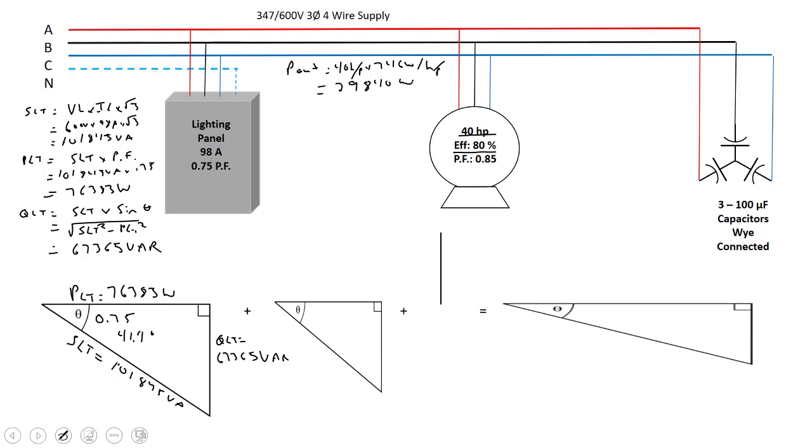All right, now I can sub that into our efficiency formula and just work it backwards. I'm just going to recall that: efficiency is power output over power input, and what I'm looking for is the power input. That's what's going to go on our power triangle. So I'm going to take my power output and divide it by my percent efficiency. That will come to approximately 37,300 watts.